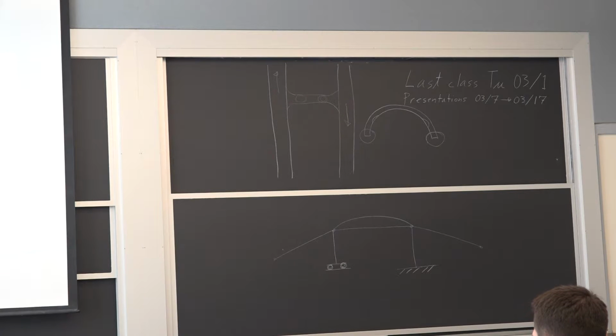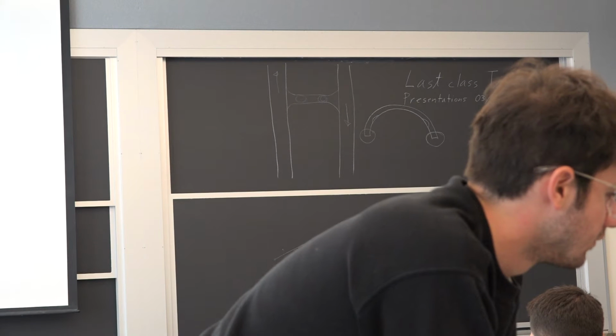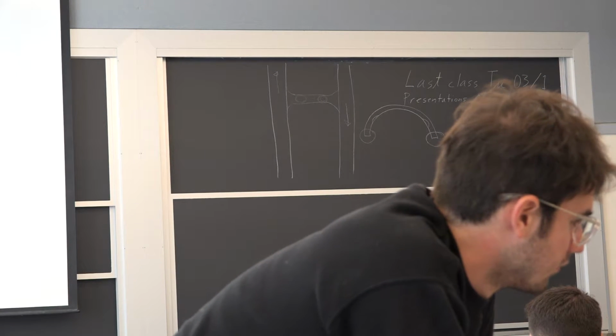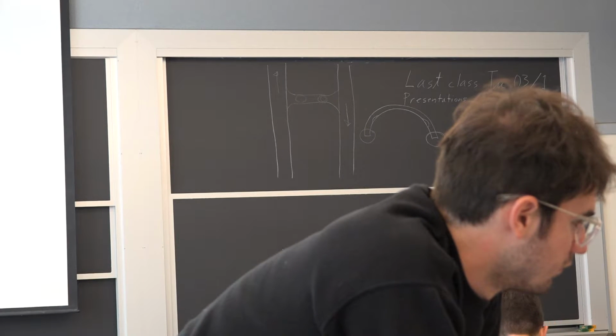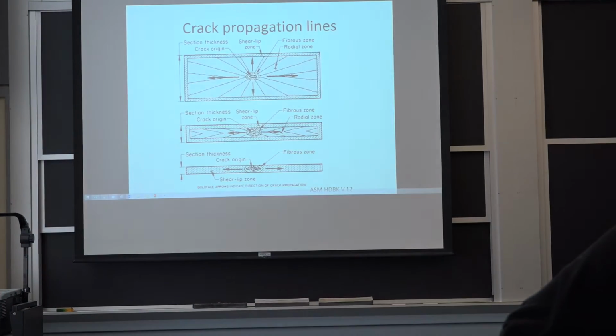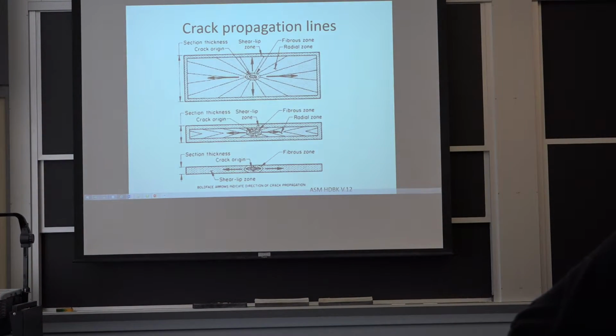So what happens to this one is just a big shaft that's under bending load, and it cracked very, very slowly. The crack started on the surface, on the outside where the stresses are higher, and it gradually came to the inside. And you see all these lines, just like tree lines, that tell you at each point in time I was at a certain penetration into the section. And the area of metal left before the final fracture is just a small little zone here in the center.